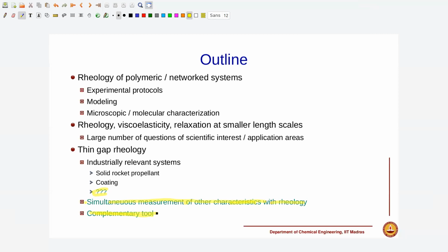The first thing is related to a model or a mechanism of how the tip and the surface you're trying to probe interact. The other thing is the response of the surface. For example, it's harder to probe some of the materials that I talked about because they are softer materials. When you probe them using a tip, the material itself can deform quite a bit, and therefore it is difficult to immediately get properties out of the force being applied on the tip.